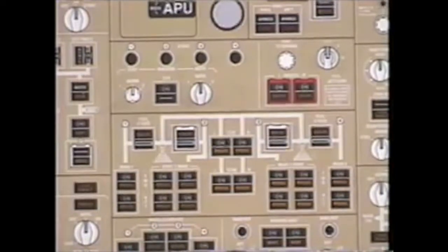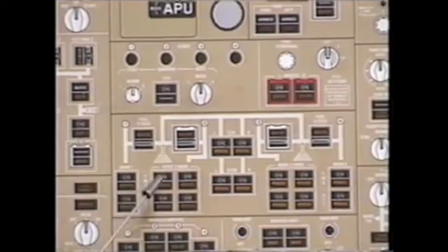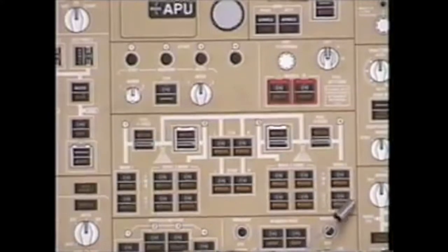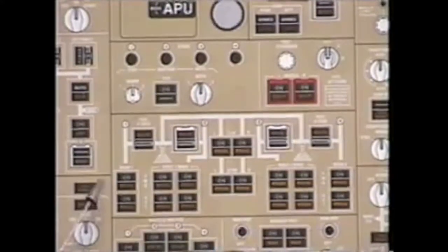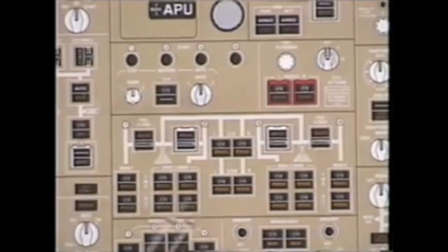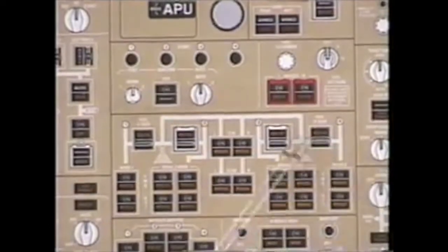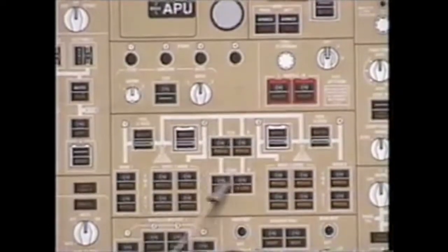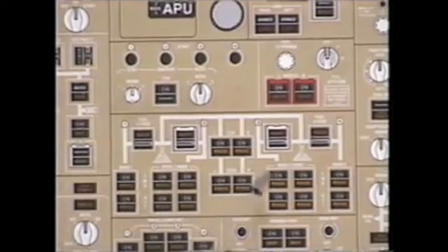There are 8 fuel tanks on your airplane, main tanks 1, 2, 3, and 4. 2 reserve tanks 2 and 3, which are physically outboard of your outboard main tanks. There's a very large center tank and a stabilizer tank. Of those 8 tanks, the only 4 tanks you can actually take the fuel out of and pump it directly overboard is the inboard mains, the center, and the stab. The stab does not transfer to the center. The stab dumps it directly overboard.